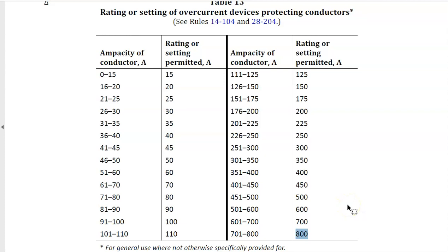Breakers are going to be available inside of any of these ones. So any of these overcurrent devices over here are available as breakers or breaker settings, as well as fuses, including this 25 amp. The 25 amp is a special one. We don't see a lot of it, but it's actually really handy for dealing with baseboard heating because we can use number 14 gauge wire, but we can load that thing up to 4,500 watts of heat off of it.